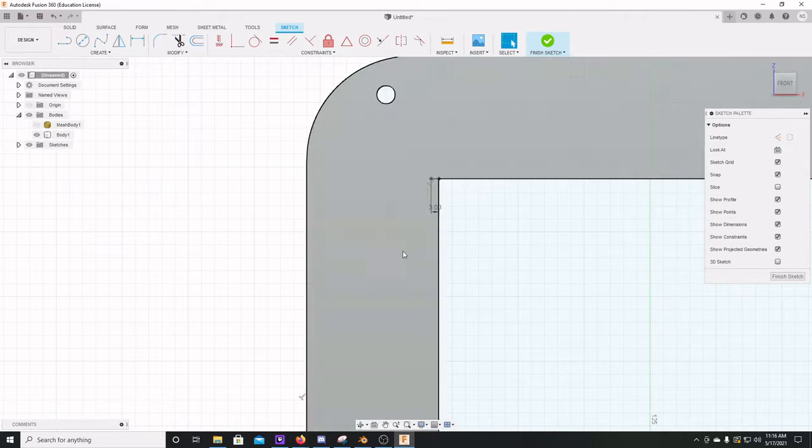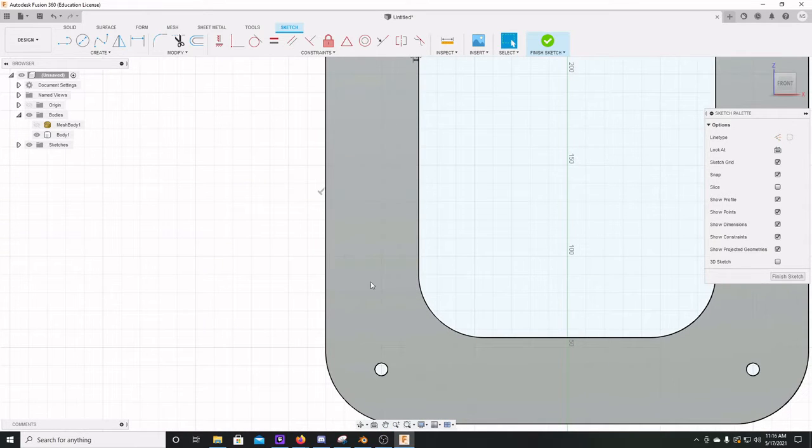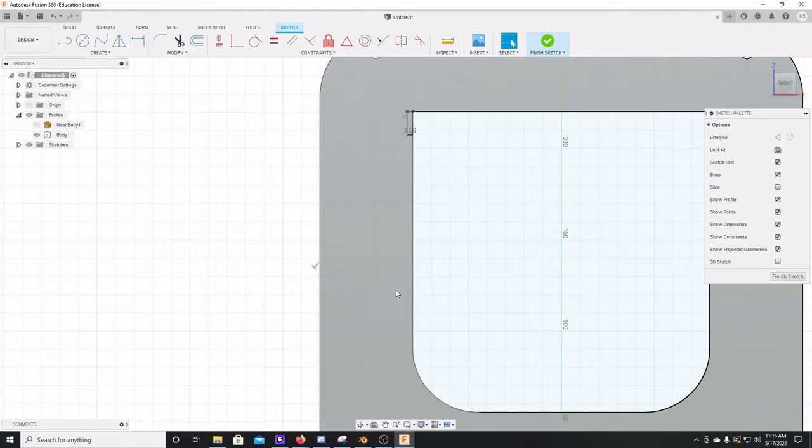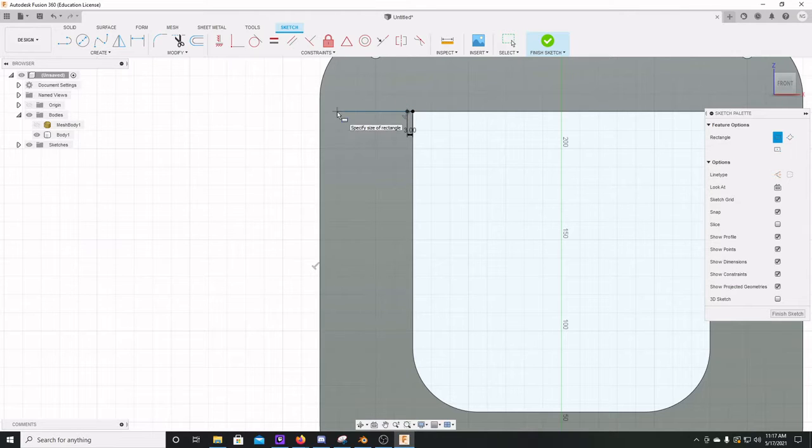Now, this whole thing is 50 across, so I'm going to make the rectangle 44 across. So there'll be 3 millimeters on each side. And I'm going to make it all the way down to here. I don't really need any more space than that. So that would be 44. There we go. 44 by, let's make it an even number, 135.